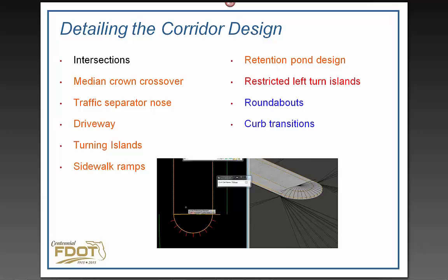So we actually have a pretty workable solution with a 3D civil cell that essentially is just a linear template that pivots, spins around itself, and completes the end of a traffic separator based on two traffic separator lines that have projected profiles to them.